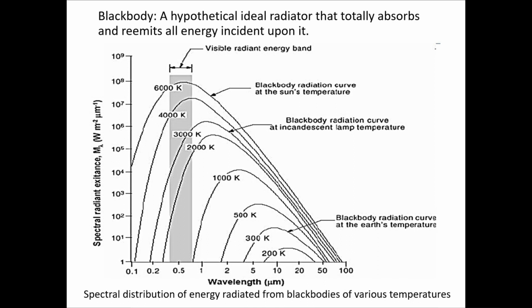Because we discussed earlier, right? Earth's ambient temperature we consider as 27 degrees. So 27 plus 273 is 300 Kelvin. You can see that curve, the second curve from the bottom. The peak of that particular curve is considered the dominant wavelength. The wavelength at which the peak of that curve occurs is called the dominant wavelength. So 9.8 micrometer is the dominant wavelength of the Earth's surface features.